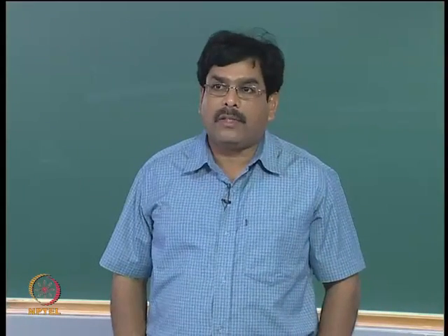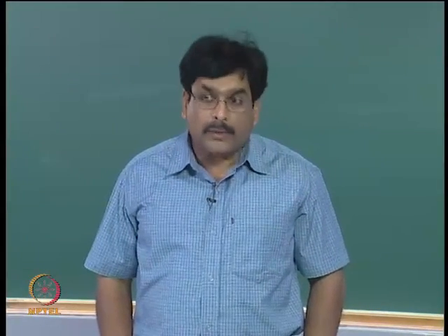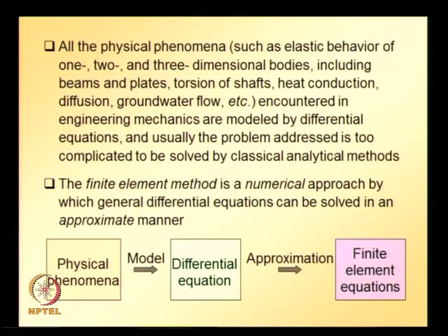Once we have the physical phenomena expressed in that form, we can use some of the classical solution techniques in conjunction with finite element method to get the finite element equations, and which we can solve for the unknowns or the solution at any point on the domain.